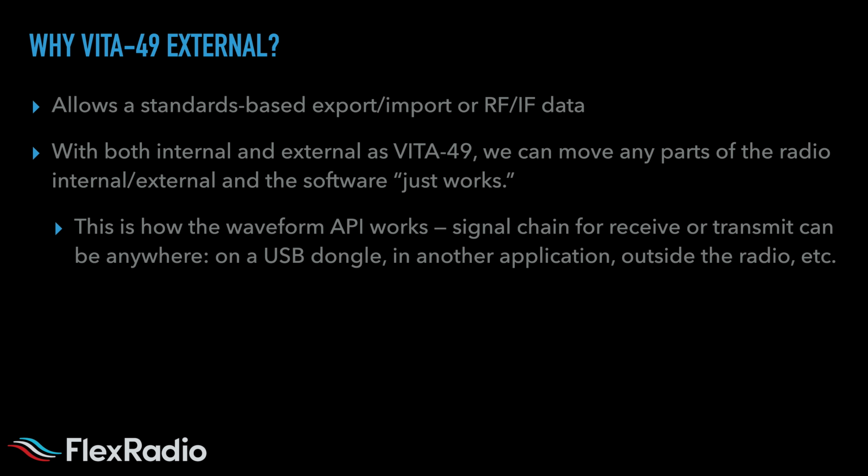An example of this is what we call the Waveform API. You may or may not have heard of this, but it's another API in our radio that allows you to add new modulation, demodulation schemes to the radio. And it's been used many times to create new capabilities for the radio. Two that are readily available for amateurs is Codec 2 FreeDV, which is a waveform that you can run inside the radio, and you can run a client outside the radio to control it, which gives you FreeDV access without any other external hardware.